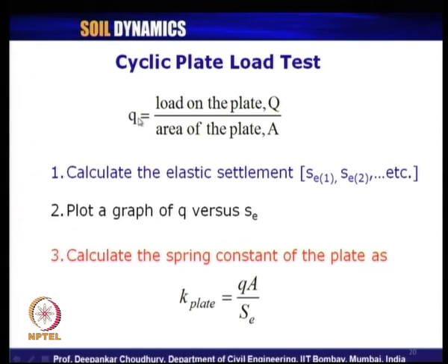The force per unit area acting on the plate is nothing but the total load applied on the plate, say capital Q, by the area of the plate. Generally, square plates are used for the plate load test. You are aware of the static plate load test. So, the same thing is used in the case of cyclic plate load test, the only change is that instead of static loading, we will apply load in cycles, we will see that.